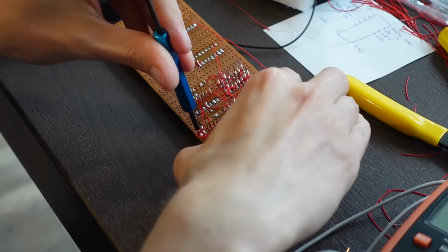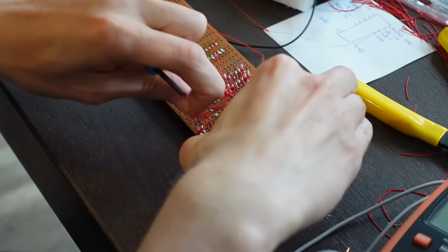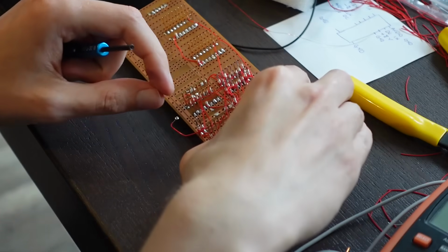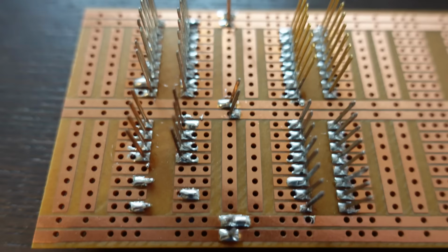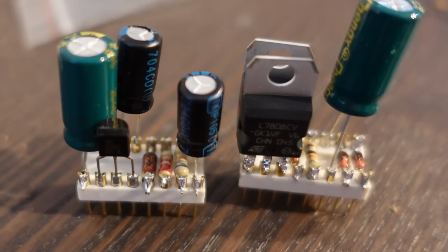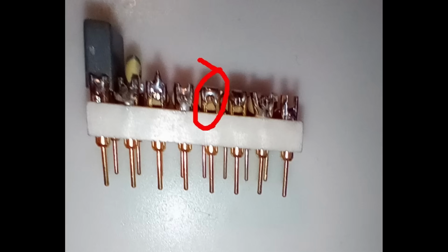I found that the most common mistake for me is when I forget that the pins are mirrored. As you wrap everything from the bottom side, the pins get flipped from how I'm used to seeing a chip. The long square posts are important, so you can't easily include passive components. Wire wrap is best suited for digital designs. I use these DIP plugs with solder lugs as a platform for passives, that I then plug into a socket. These were great in some ways, but I did have a few problems with bad soldering that wasn't immediately obvious.